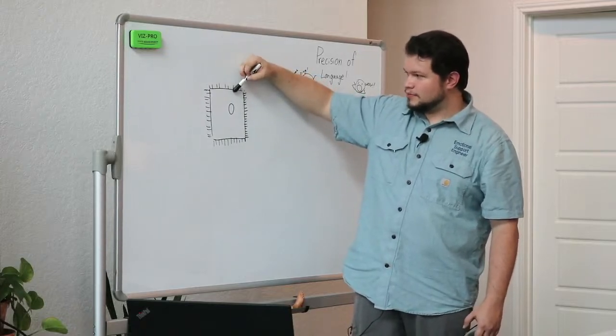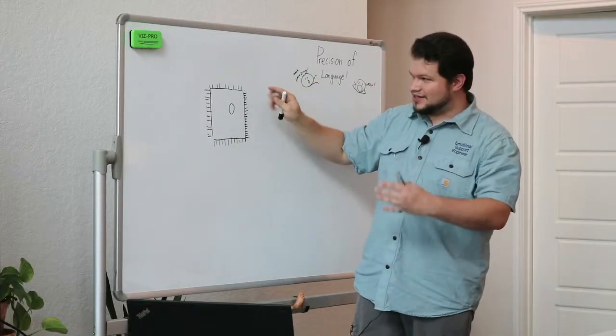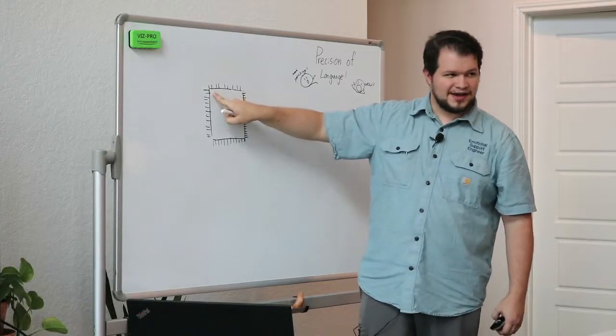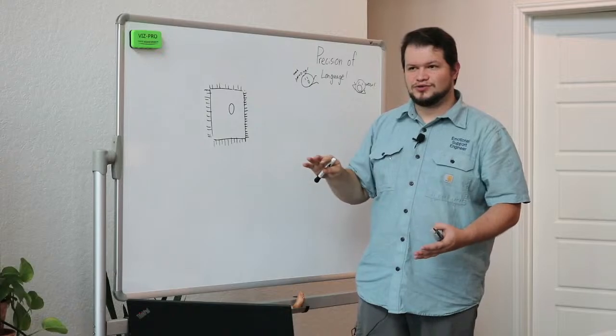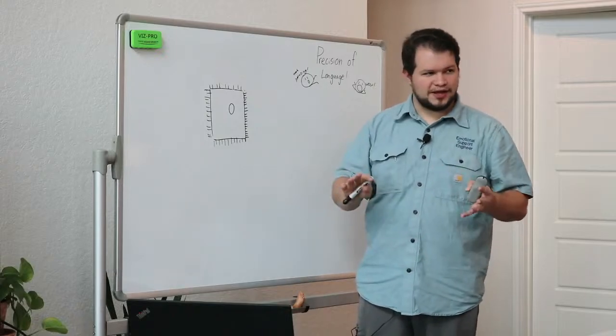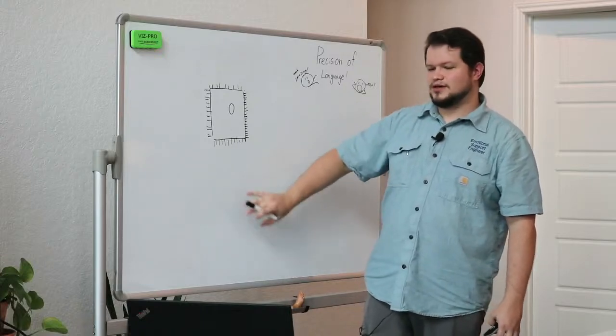And so it knows that the bubble is right there because that current is not being seen. And so as you tilt this, that bubble will move to the other pins, and you can track where this bubble is, which directly translates to where you are in space, what angle you are. It's almost like a poor man's gyroscope in a sense.